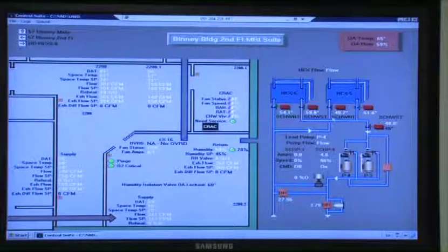Well, let us know that, because then when we go to the 4th floor graphic of the water system, we can put that right on there. It looks like a manual changeover for both heat exchangers. They're all reading pretty low temperatures, so everything's probably open, but you can obviously manually valve them off. There are no isolation valves to isolate one, automation-wise, and there are no Belimos in there. They're just regular hand shut-off valves on all the heat exchangers in here. Heat exchangers 1, 2, and 3, same thing. It's all manually done. Excellent.